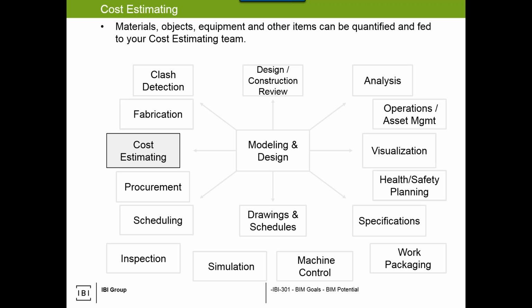So instead of just a wall, if in Revit I have enough family delineation so that I know that it is a concrete wall, brick wall, mason CMU wall, or I know the assembly of the wall based on wall types, it'll enhance what the estimator can then do with that information. Same with piping. If I know that it's carbon steel versus high density FRP versus stainless steel, I'll know the range of the material costs based on what's flowing within, and that'll help to drive the costing.